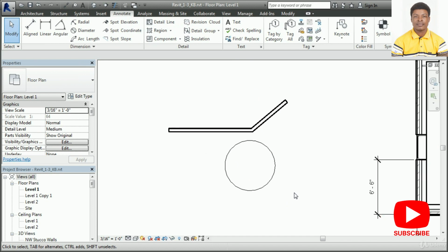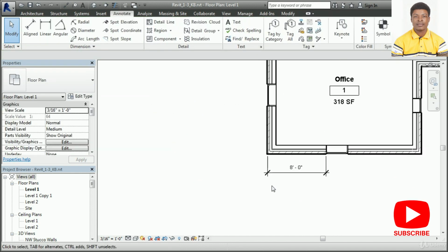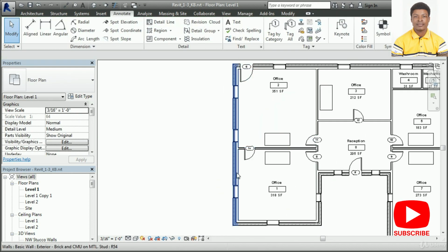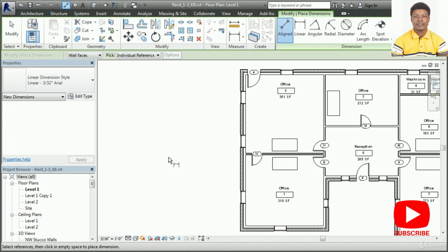You can add dimensions to individual faces. You can also add dimensions in a series by selecting an entire wall. And let's see how we can show this. Let's take this string here. This shows an intersecting wall on the inside and some openings on the outside. When I choose my Align Dimension tool, the options bar shows the ability for me to choose wall center lines, wall faces, center of core, or faces of core. And it will default to a center line. I'm going to change that to wall faces.